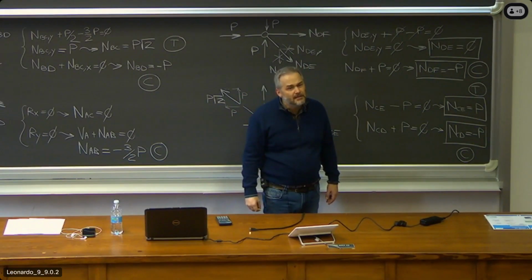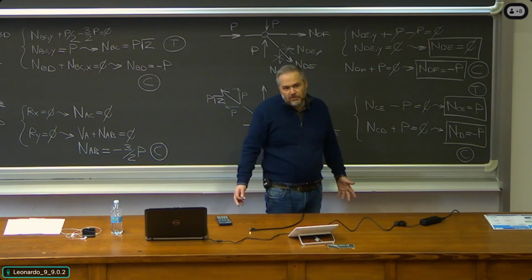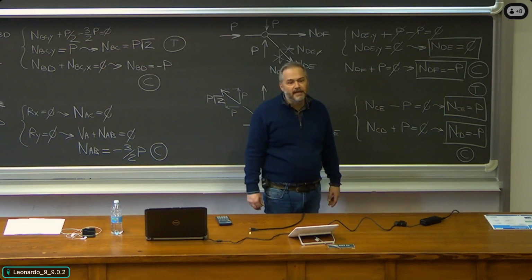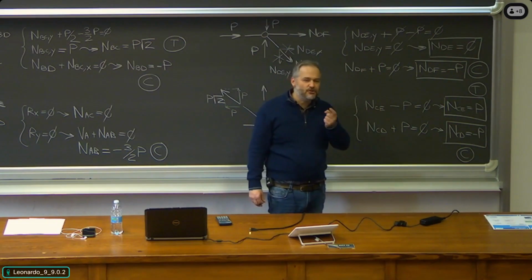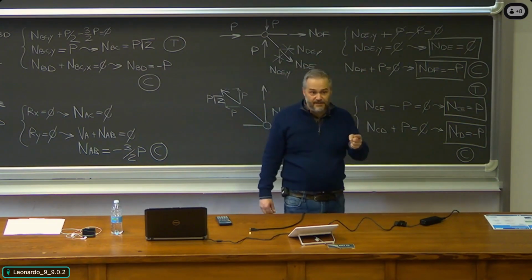And if the member equals 0, what is considered? Compression or tension? If you have the number 0, do you consider it to be positive or negative? Both or none of them. So we simply don't care, because we care about compression or tension since the design process involved is then different.